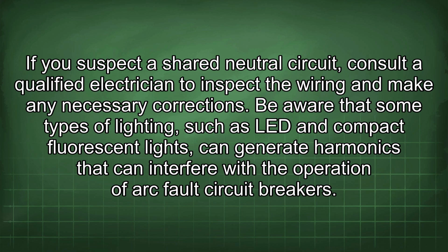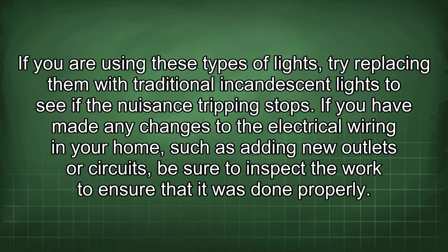Be aware that some types of lighting, such as LED and compact fluorescent lights, can generate harmonics that can interfere with the operation of arc fault circuit breakers. If you are using these types of lights, try replacing them with traditional incandescent lights to see if the nuisance